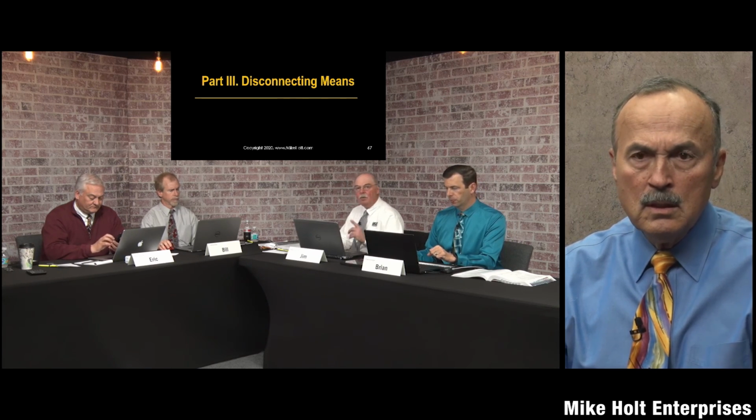Part 2. So we just got done with whatever that was on the circuits. One other thing on the initiating device, Mike, is that on a 1 or 2 family dwelling, I started to mention this earlier, it's required to be on the exterior of a 1 or 2 family dwelling. Okay, so we need to make sure that's in my textbook, Brian. What rule is that, Jimmy? That's 690.12C. It's C, the main body. If it's a 1 or 2 family dwelling, that initiating device has to be on the outside of the building.